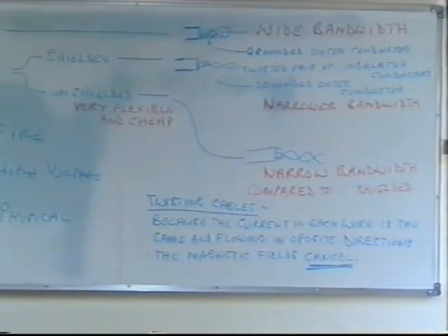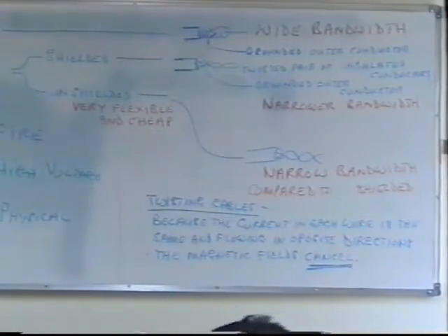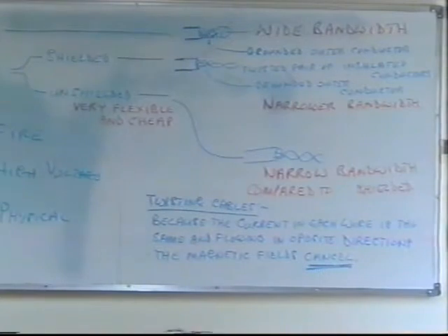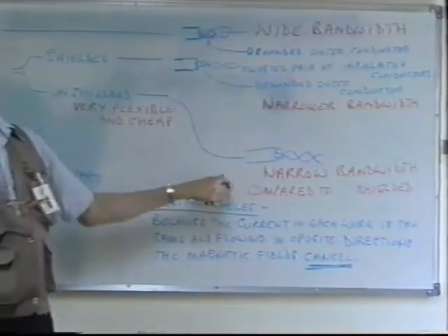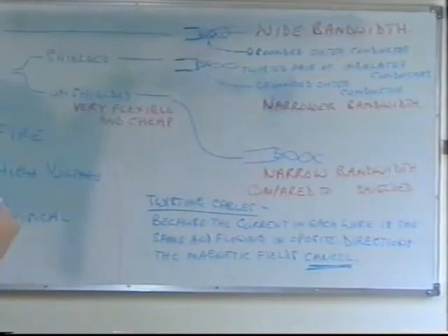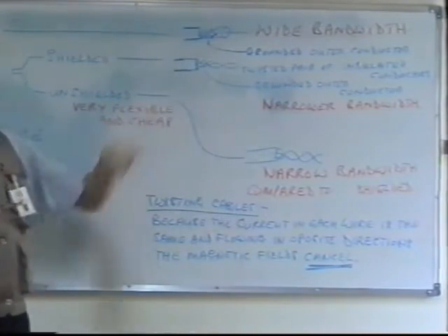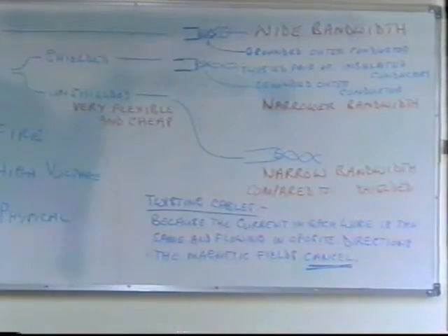Shield. Not interference. That's right. Even without the shield here, you cut down on the noise and you get a wider bandwidth than you would without the twisting. But the shield protects the twisted pair even better, gives you even greater noise immunity and a wider bandwidth.